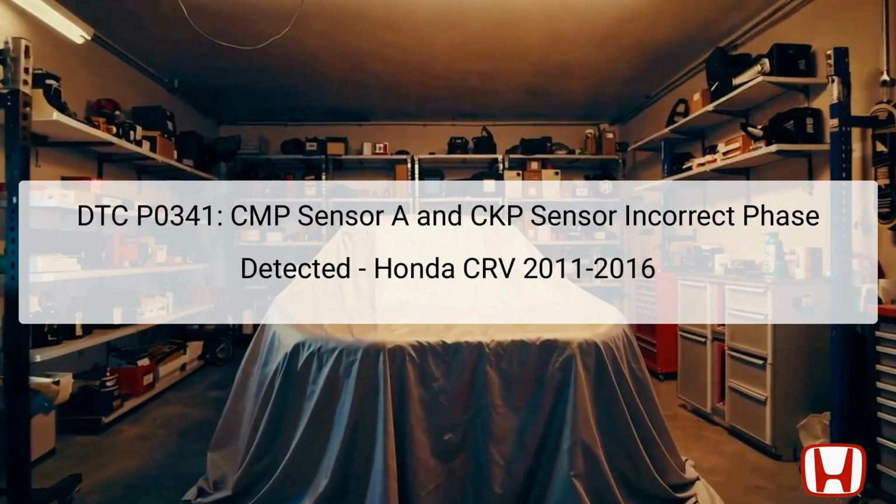DTC P0341 refers to a malfunction with the Camshaft Position (CMP) sensor A and the Crankshaft Position (CKP) sensor, indicating an incorrect phase is detected between these components. This issue can potentially affect the engine's timing and performance due to the critical role these sensors play in the engine management system. The CMP sensor is typically located near the camshaft, while the CKP sensor is positioned near the crankshaft, making both pivotal in monitoring engine rotation and position.